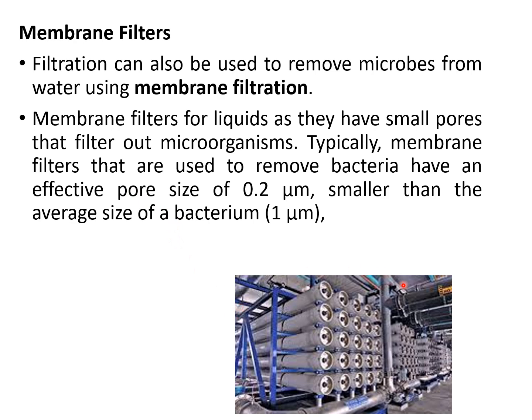In industries, membrane filters are used to remove microorganisms from water. For liquids like water, it goes through the small pores and microorganisms get blocked because the pore size of these filters is less than 0.2 micrometers, while the smallest average bacterium size is 1 micrometer. As the water is moving through the filters, the microorganisms are retained while only the filtered water moves through, and such water is used in food preparation.